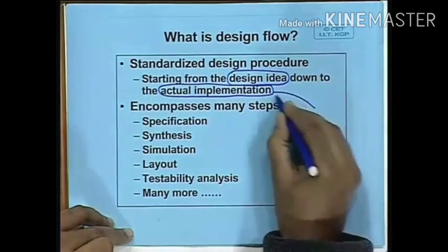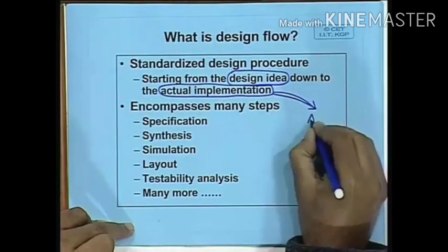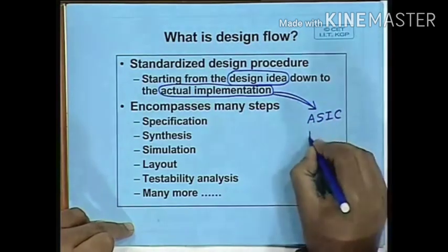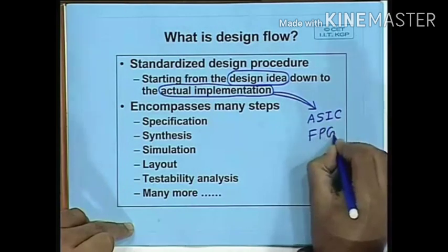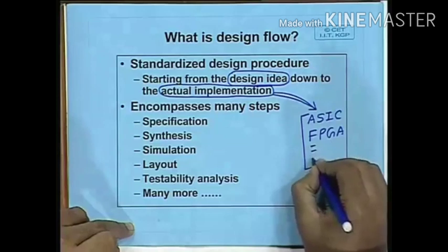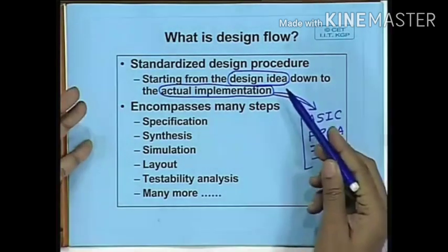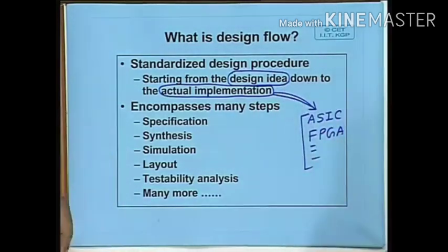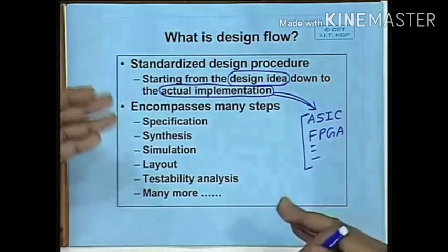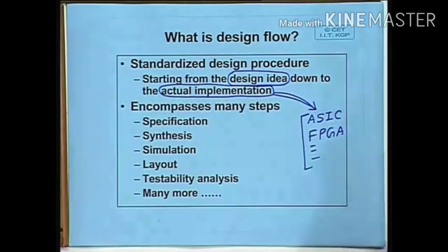Now, when we are talking about actual implementation, again I have told you this can be an application specific integrated circuit, it can be a field programmable gate array, or it can be any other kind of programmable logic like PLDs or any other thing. But the idea is this: you have a design idea which you specify in some form, and using a sequence of steps using the CAD tools, you finally arrive at the actual implementation at the very end.